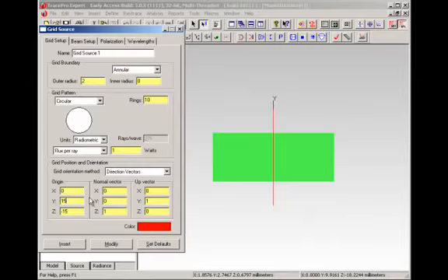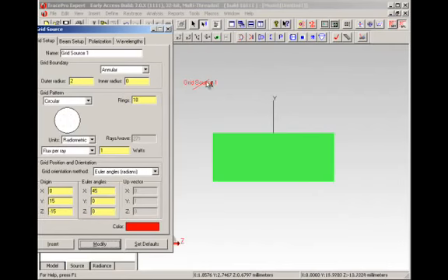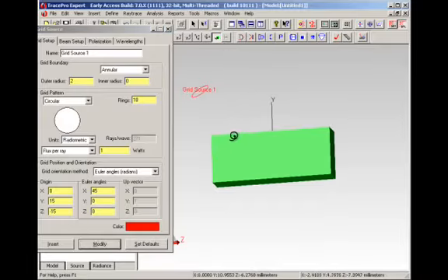So it starts off, hopefully, going downwards 45 degrees around the x-axis towards my particular surface. The reason why I'm doing this is that it's going to create a grid up above, and we can see it up here when we hit the Modify button, that it's going to come and it's going to hit both of these surfaces.